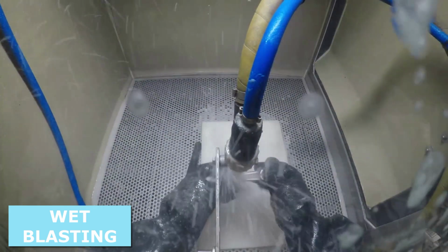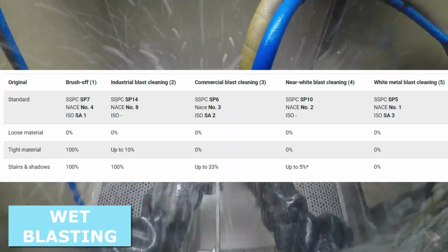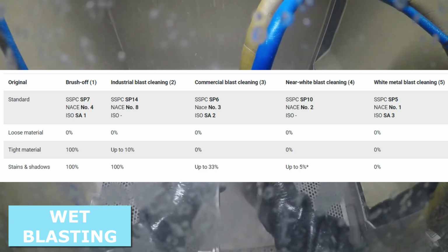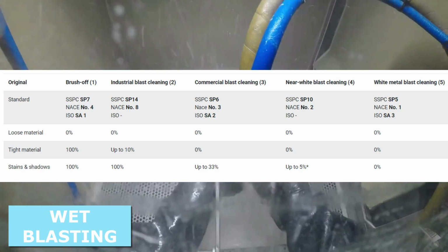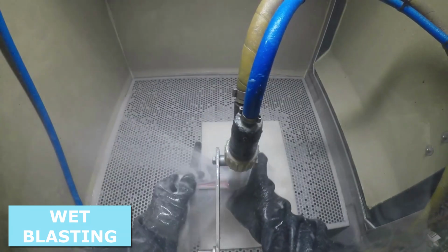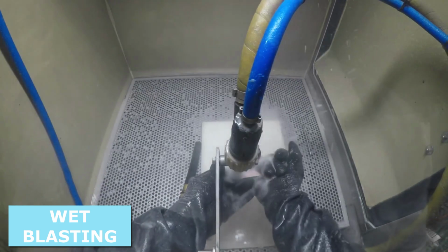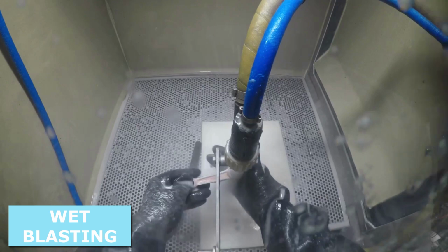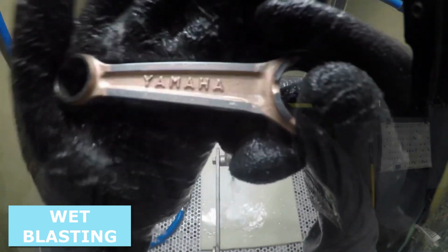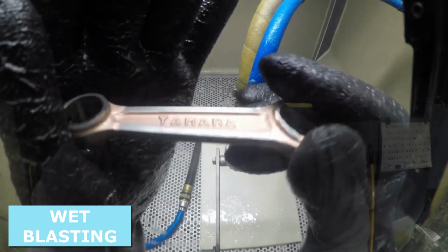Surface profile. In the blast cleaning process, grains of abrasive are propelled with great force and energy at work surfaces. Upon impact, the grains dig into the surface and then rebound out, leaving a rugged, miniature mountain and valley finish. This surface structure is expressed by the surface profile, which measures the size of the shapes created. The surface profile is critical to coating performance as it increases the surface area and provides a key tooth anchor pattern for the coating to adhere to.